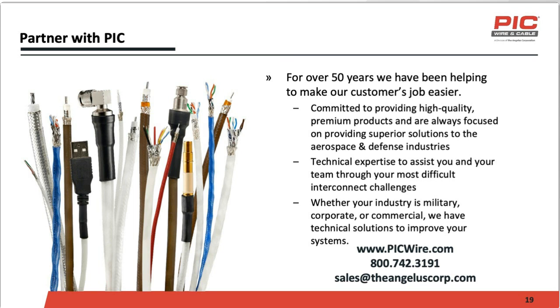Another great question. MACHFORCE takes roughly 12 minutes per port to terminate. And there's a lot of advantages that play into that termination time, including the fact that you utilize standard stripping and crimping tools to crimp on standard 22D contacts. So there's no soldering involved. And that makes field termination much easier, and it actually makes termination and repair of connectors in the field possible.